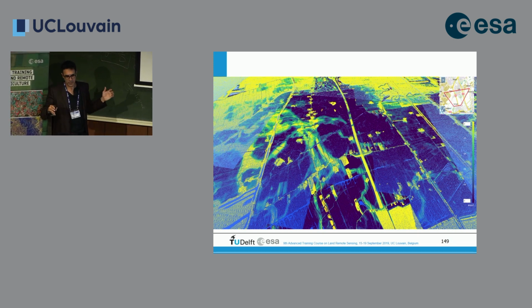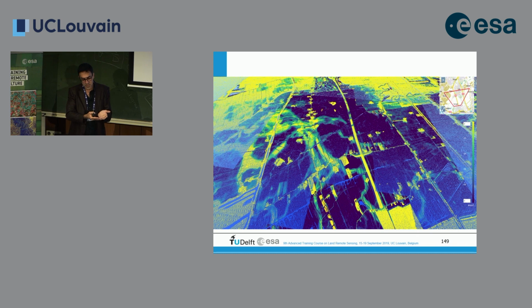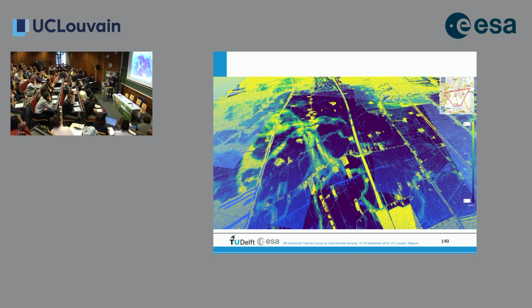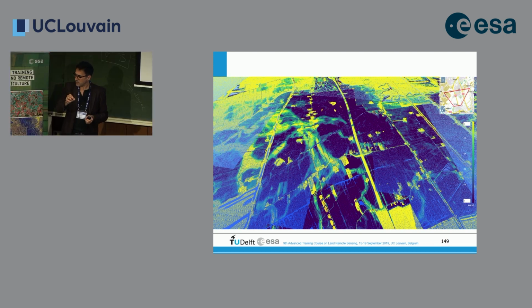This is because this was a sea level area where the sea came in, deposited sand, and the sea went back, and so the sand remained. What used to be creeks, shallow areas where the sea went in and out and sand was deposited, now become little mountains because the creeks are filled with sand, and the rest is peat. So the peat goes away, the sand stays. And this is why we see this. Now, the consequence is that if we look at the subsidence of this area, we expect much more subsidence here and here and here than here. If there are sandy soils, it will not subside that fast. So in this area, it's not only very difficult to measure something because of the techniques, but we also need to have a pretty high resolution because it differs from location to location.